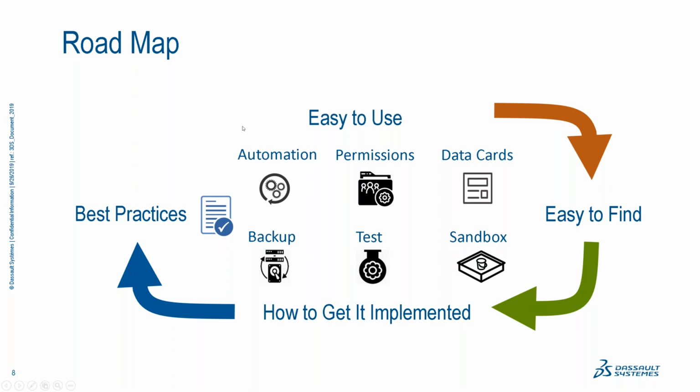Take advantage of automation, because you can actually have signatures and revision numbers automatically stamped on the drawing title block. So there is no user interaction, there are no manual entries of that data. In addition to that, when you actually release one of your SOLIDWORKS drawings in the system, a PDF can automatically be generated so other users can actually consume the data.